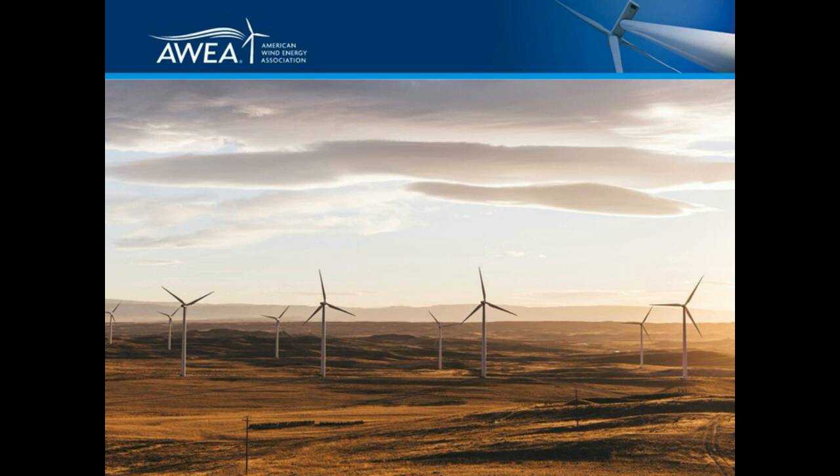Yeah, great question. We've done quite a bit of work looking at capacity factors in the U.S. in our annual market report. And it's interesting, in 2015, if you look across the entire fleet, capacity factor was about 32%. But I don't think that tells the full story, because we've got a lot of old turbines that were built in the 80s and early 90s that are continuing to operate that certainly bring that average capacity factor down. So one thing that we do is look at capacity factors by vintage year, the year in which the project was commissioned.